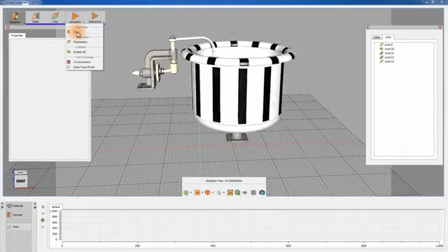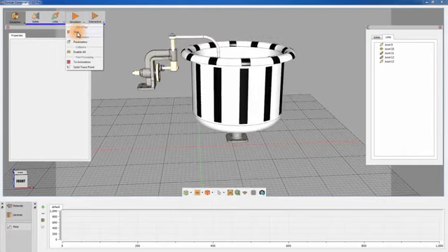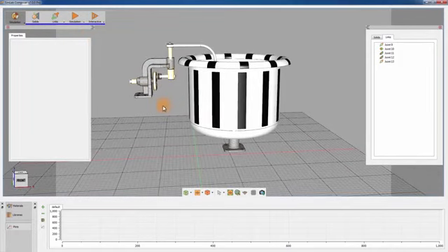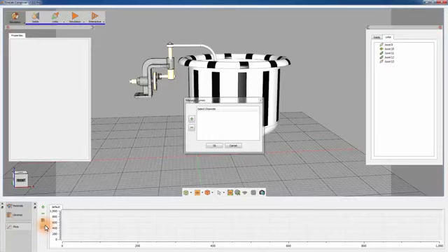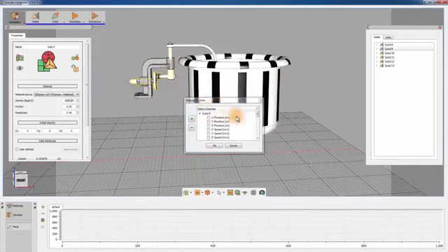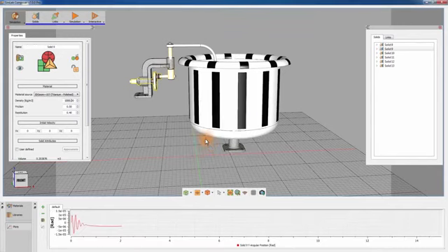An additional feature the SimLab Composer simulation offers is creating an analysis diagram for the simulation. From the Plots panel, select Manage Curves. Click on the Add Channel icon, and then select the solid of which its data needs to be analyzed. Select which property you need to display for the solid. You can either select one attribute to display in the diagram, or you can display multiple attributes for the same solid at once. Click OK and play the simulation.